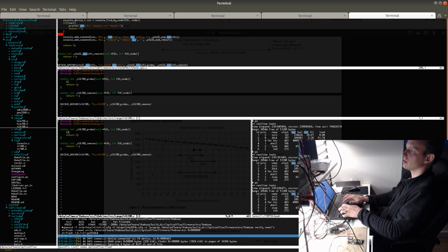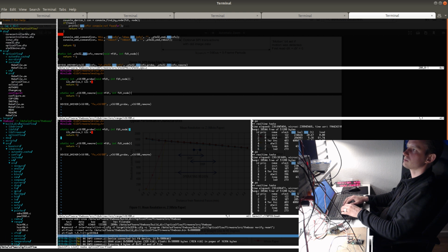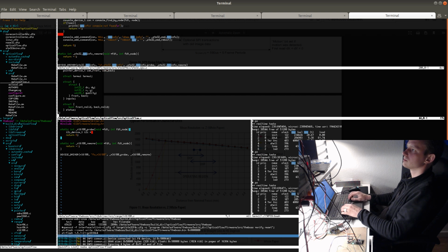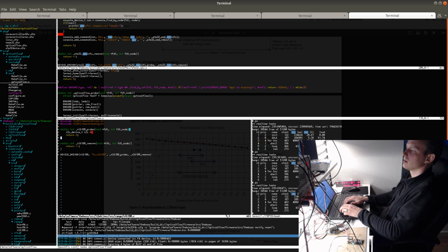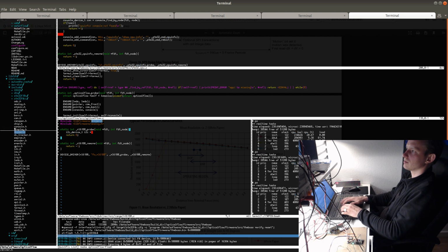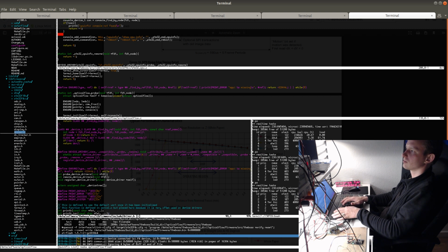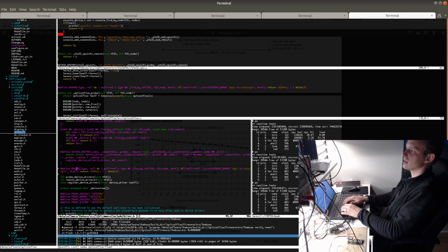In the probe method, I'm going to get the I2C device, which is going to be, let's see. Actually, I have a few macros that I've defined for this other driver. Let's see here, where did I put them? Which I think I'm going to reuse. Actually, this macro. And I'm going to place this into the driver header file. And this will provide a generic way of getting the variables from the device tree and fetching them into the local object for the device driver, the instance of the device driver.